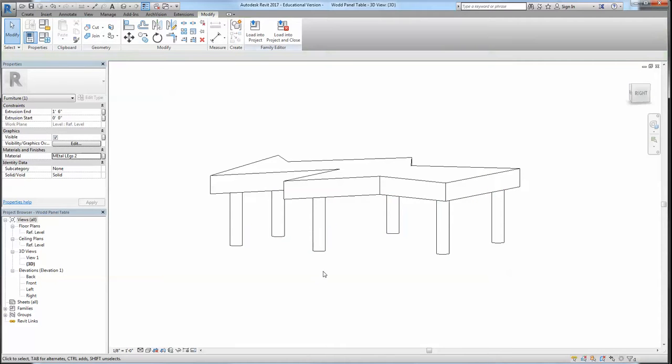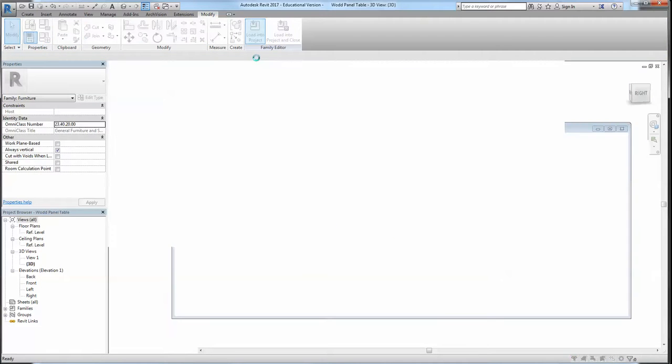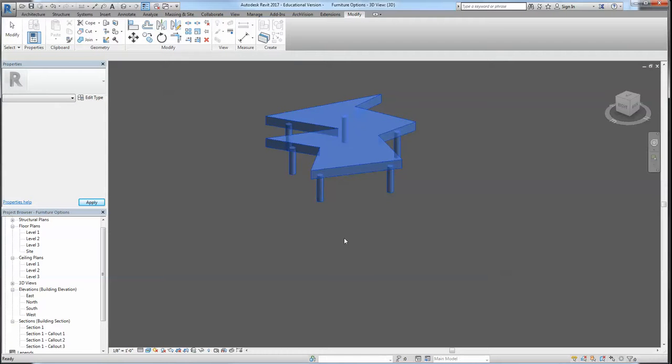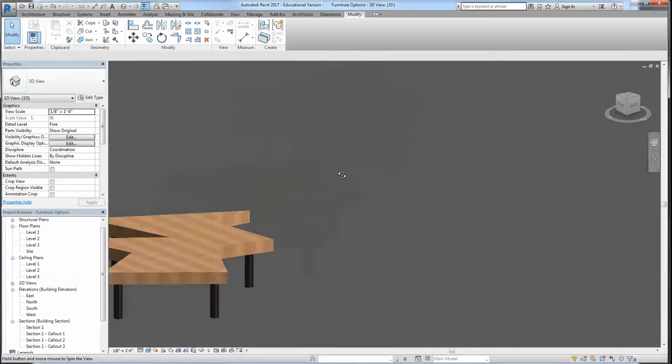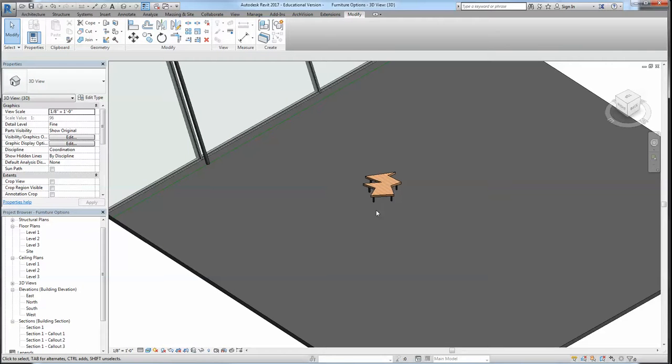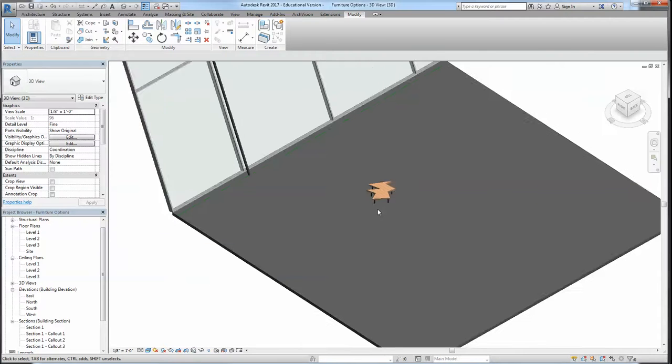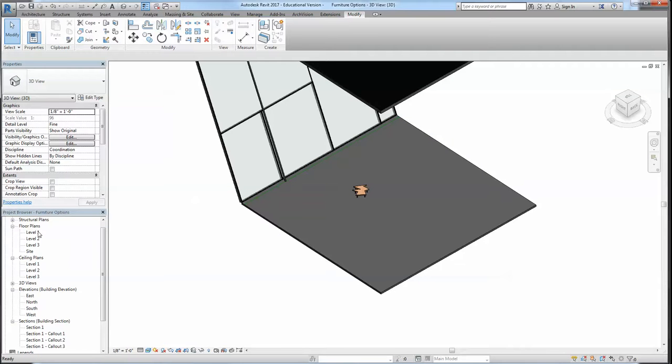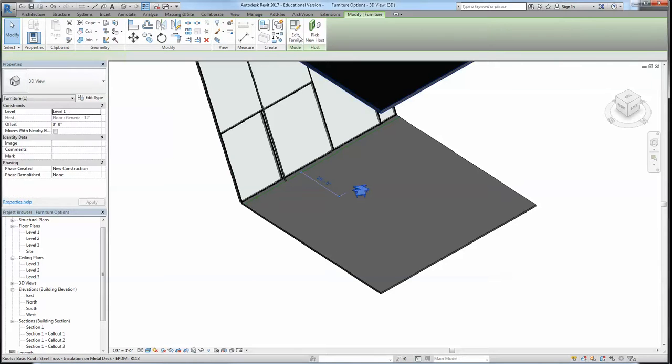Okay, you save it again, load it, override. There we go. So you render this, that would be a nice material. Okay, so with extrusion you can do shelves, you can do pretty much anything, most of the things that you can imagine. So I say that if you know extrusion, you know pretty much 90% of that interface. But what if you want to actually work, instead of, for example, from plan, let me actually edit this family.